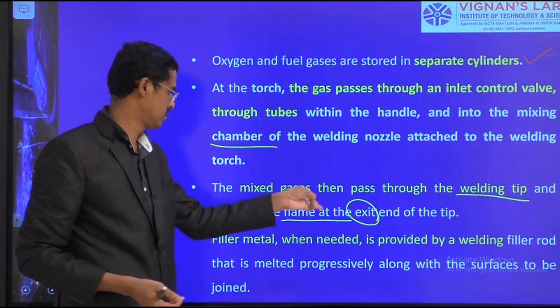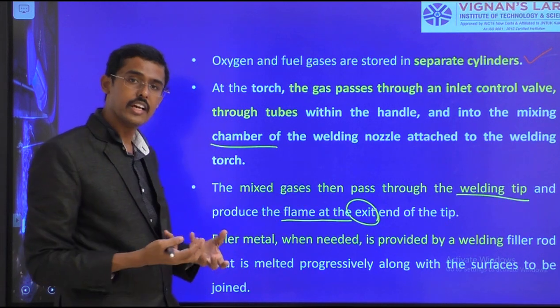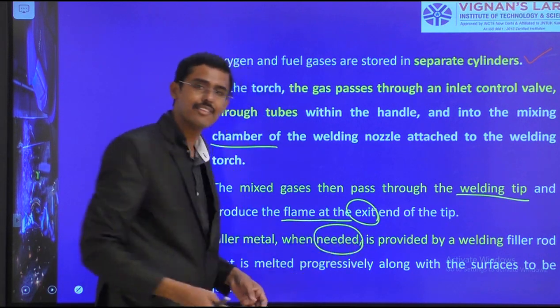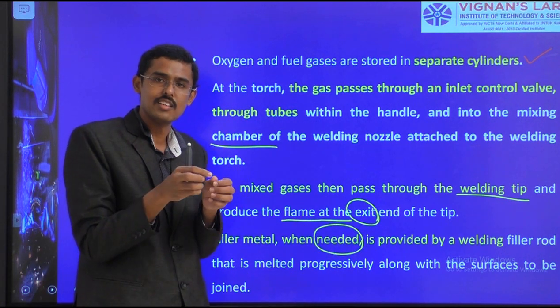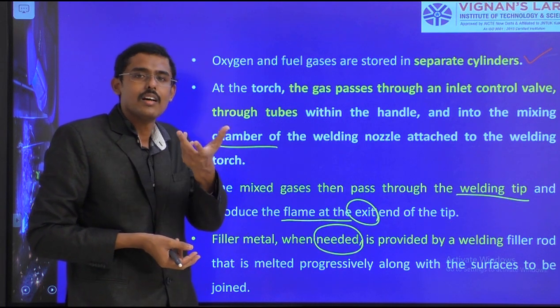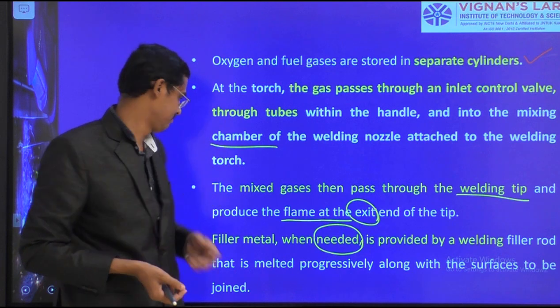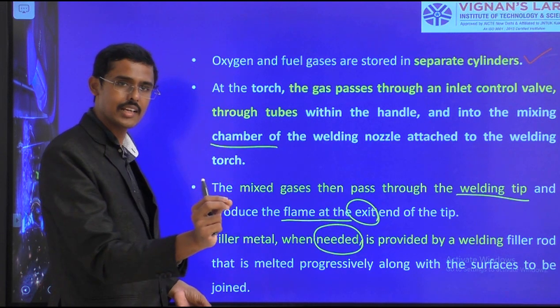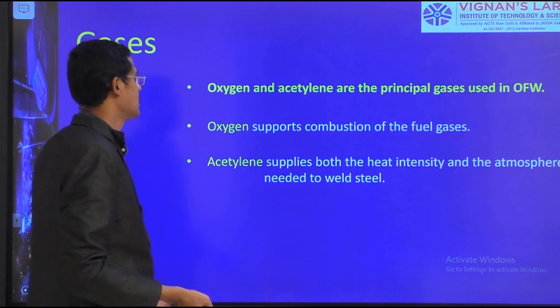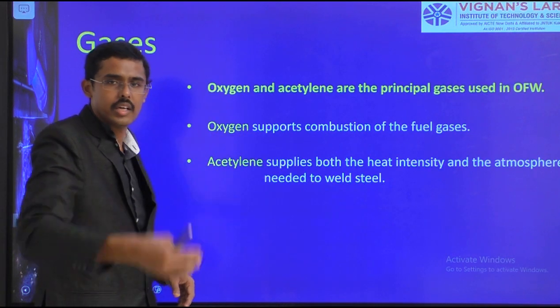Maybe these three flames. Filler metal is added if needed, for welding thicker material. For thinner material, autogenous welding can be done: just light heating, and the material lightly melts and is welded. In such cases, no filler is needed.